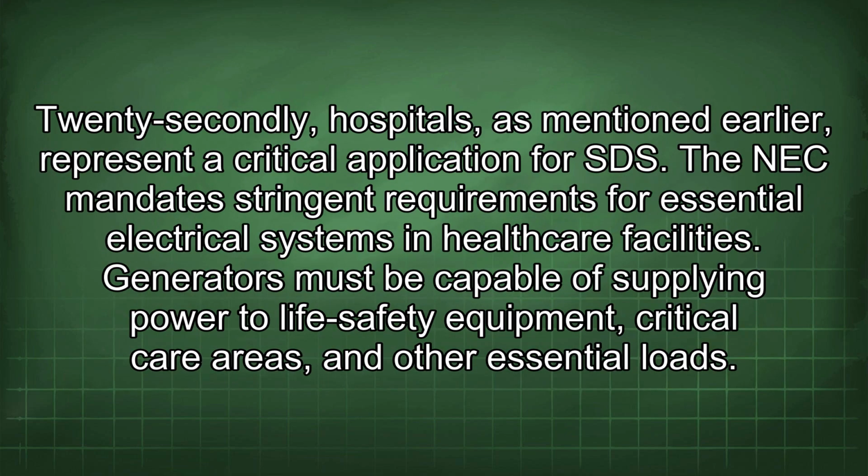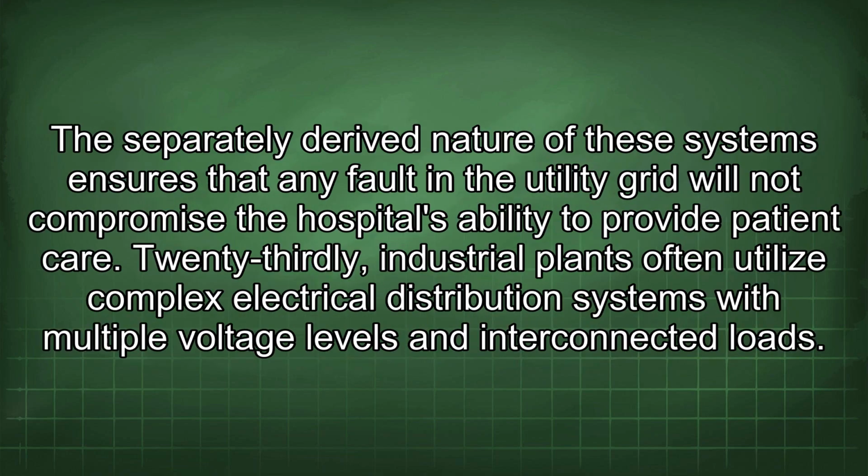Twenty-secondly, hospitals, as mentioned earlier, represent a critical application for SDS. The NEC mandates stringent requirements for essential electrical systems in healthcare facilities. Generators must be capable of supplying power to life safety equipment, critical care areas, and other essential loads. The separately derived nature of these systems ensures that any fault in the utility grid will not compromise the hospital's ability to provide patient care.